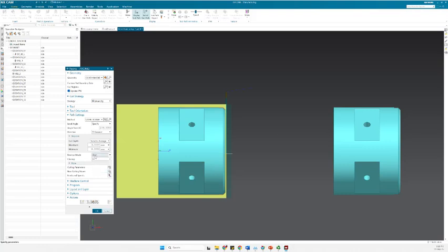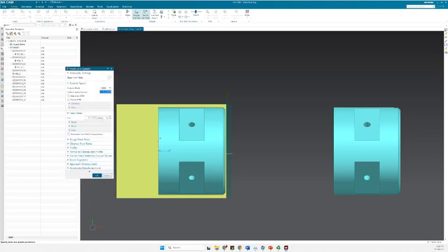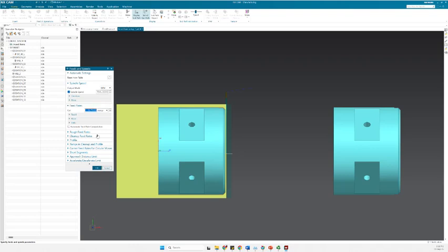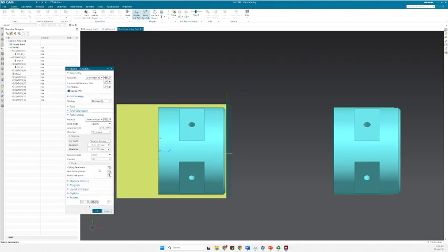We could also put this one as omit, as it is here. I don't want to repeat that, but anyway, better to repeat it rather than miss it. You can define the feed and speed here. So what is your spindle speed? For example, in terms of RPM, let's say 750. These are something that you calculate. The feed rate, you need to see from the tool, based on the catalog that you are using, the type of tools and the material that we are machining. You can figure this out and put in the right number.